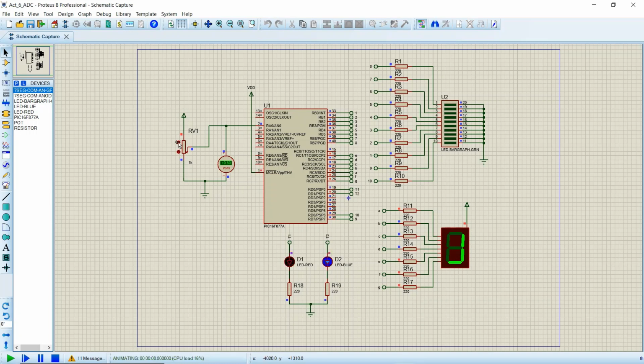And if we increase this value, we're going to see that it turns on the first LED, the second one, the third one, and when it reaches a voltage level higher than or equal to 2.5, it will indicate that it's a high level, or it's enough light in the area, and the LEDs will stop toggling. If we decrease the value, the LEDs start toggling again and indicate that it's a low value. So if we keep increasing, it will tell us that it's enough light or it's a high state.